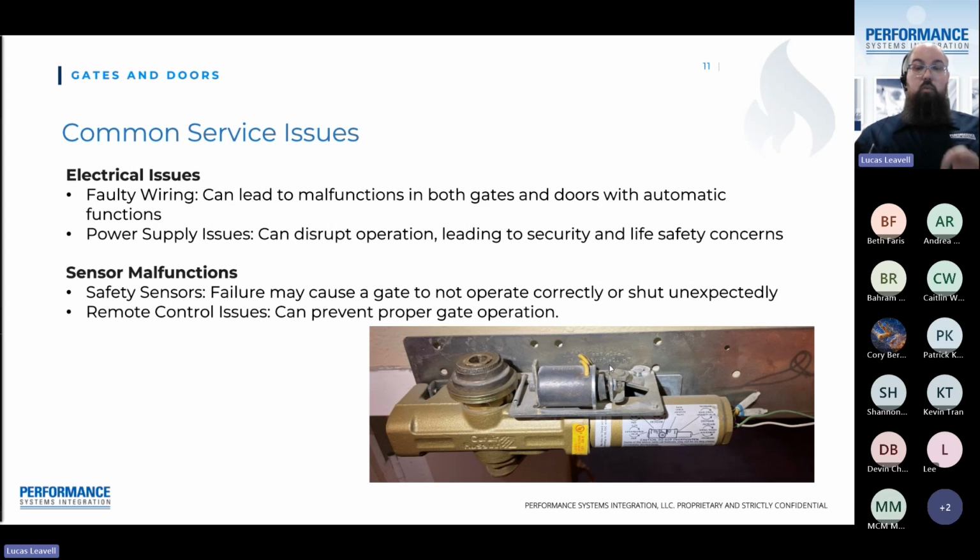When you push a button, it turns the operator on and allows it to move. This is a little solenoid that does that for it. Otherwise, the door would remain open. However, this is a point that will get hot over time. As it gets hot, the solenoid will no longer work properly. These are common failures, especially in older components.